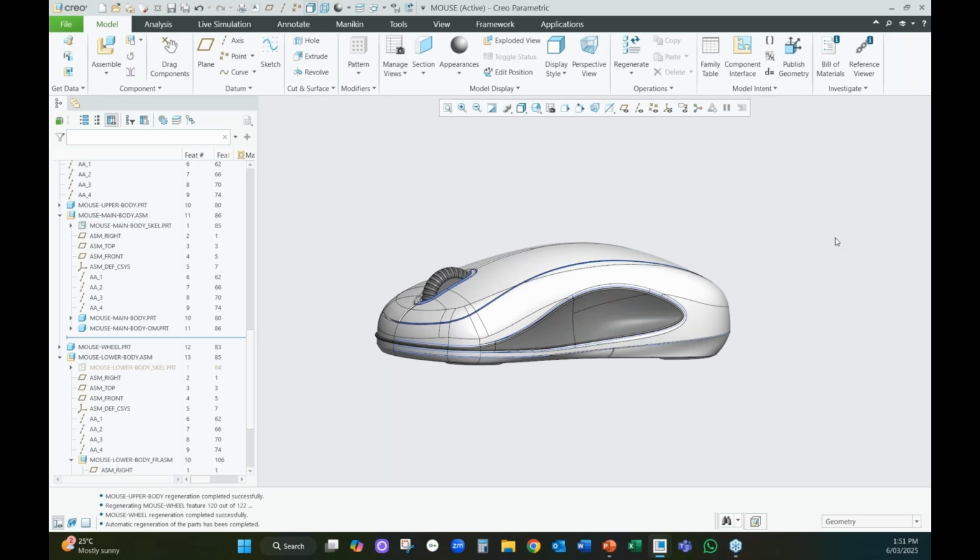That being said, though, it's not a set and forget. This is a living CAD file, and I'm constantly going back into the skeleton and adding new data where two or more parts are sharing that geometry or interacting with each other through that geometry, similar to that part line example that I showed before. And so you're really looking to try and crystal ball gaze your interactions of your parts. But once you've created something with a top-down design reference, you can also go and break it later if you need to. So it's not set in stone. It's really a live, fluid model structure.